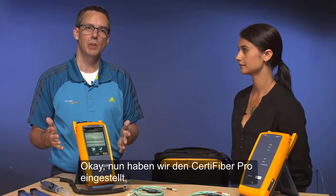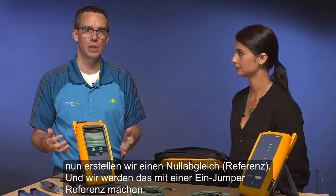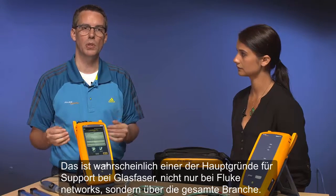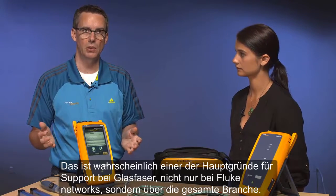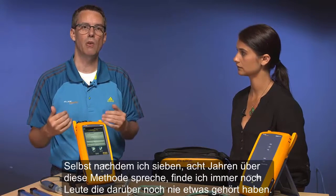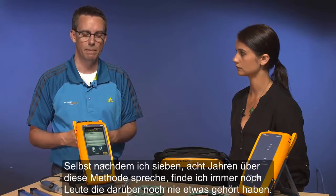Okay, so now we set up the CertiFiber Pro, we're going to set a reference and we're going to do this one jumper reference. This has to be probably one of the single largest causes of support in fiber testing, not just at Fluke Networks, but right across the industry. Even after 7-8 years of talking about this method, I still find myself teaching it to people that have never ever done it this way.